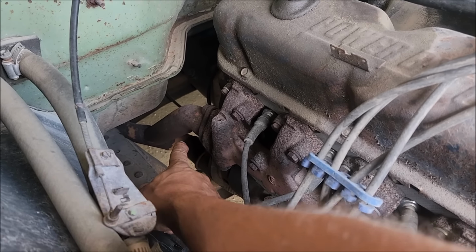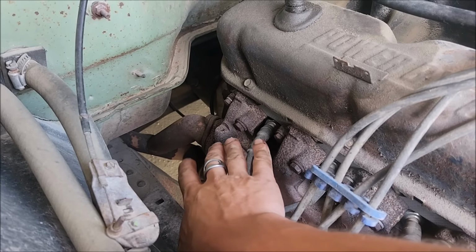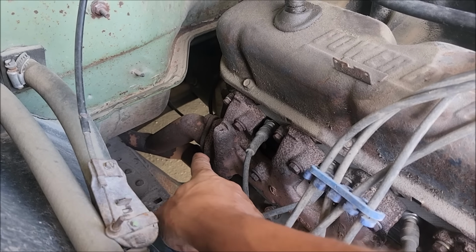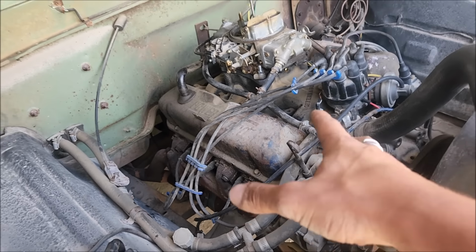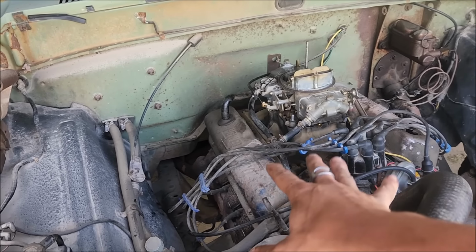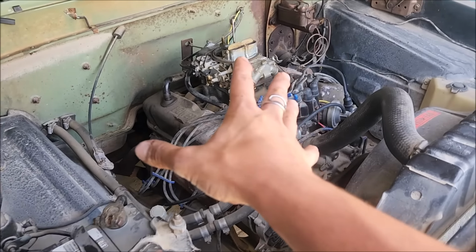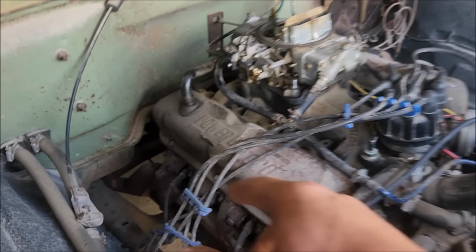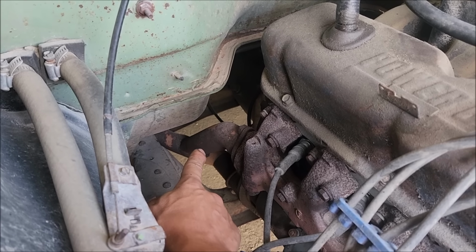So in this case, we're going to target this one tube from our passenger side cylinder bank. A lot of folks get tripped up because they think that they need a signal from both banks. Dual planes, single planes, both sides of the carb feed one side of the engine depending on the cylinder. You'll see on dual planes the intake runners wrap around and everything. So unless you have a dead cylinder via ignition, everything should be equal if your carb is adjusted evenly, which it should be if you're doing it right.